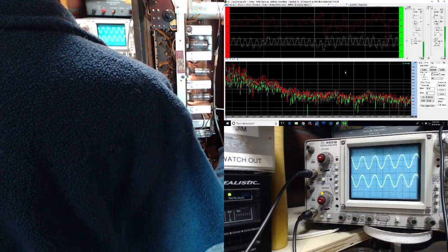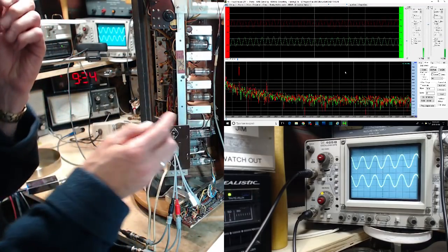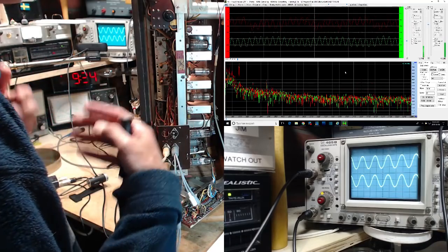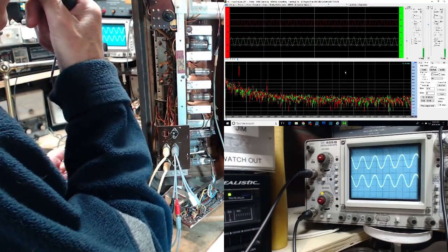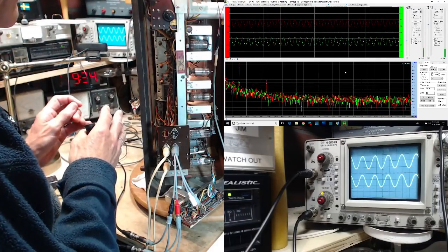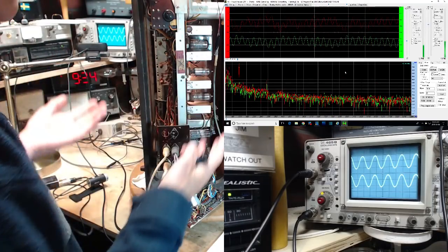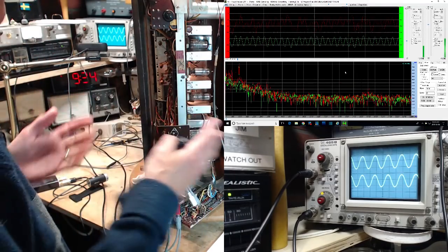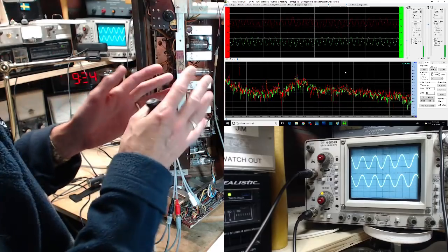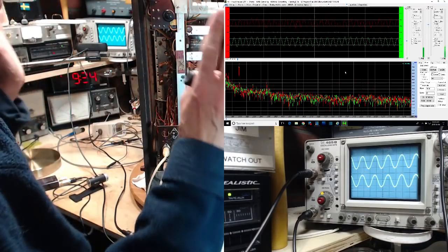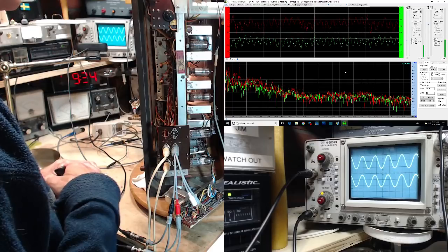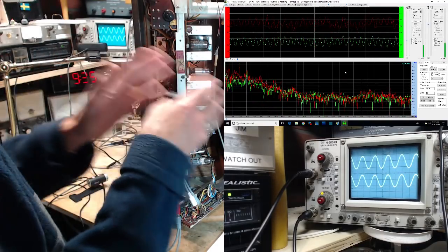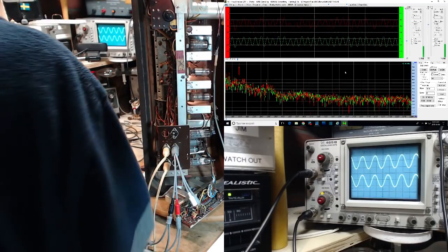So I think I know what the lesson is here. The lesson is distortions at lower frequencies produce harmonics that are more in the range of your hearing. So it's the lower frequencies that are going to sound off, if you like. And of course, when you're listening to music, you can't sort all that out in your head while you're listening, unless the music is very specific. But if it's just a jumble of sounds, you're really going to have a hard time spotting that the lower tones have harmonics, annoying grating harmonics.